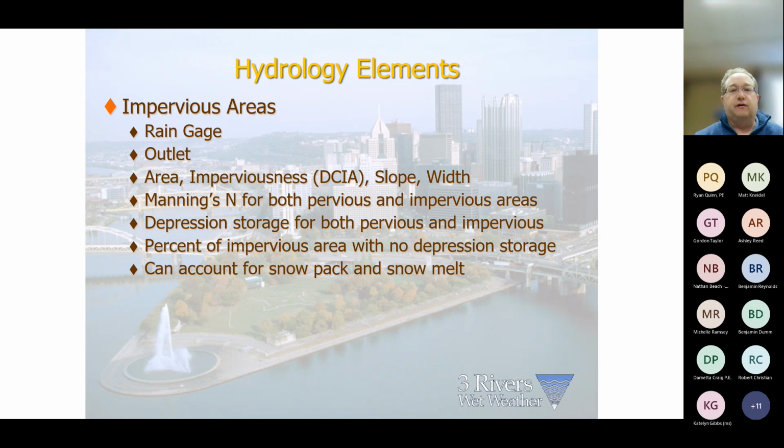The other things that are sensitive are slope and width. You will notice in the model, depending on where your system is, quite often the subcatchments for the impervious areas are broken up into slope categories. So high slope, medium slope, low slope, there's actually more categories than that, that then have their own widths and information tied to that. There are a few areas that just have one subcatchment represented with an average slope for that condition. Those subcatchments are on top of one another.